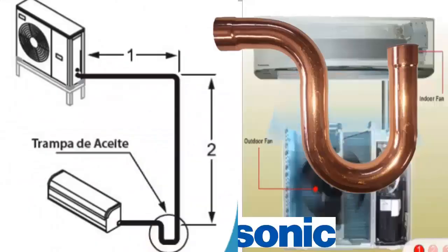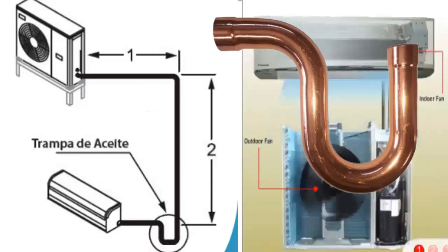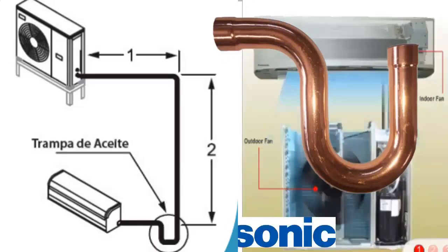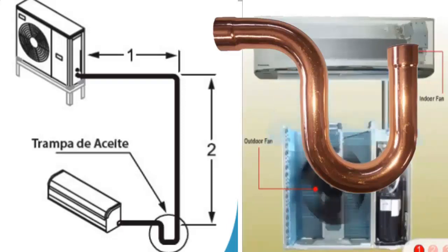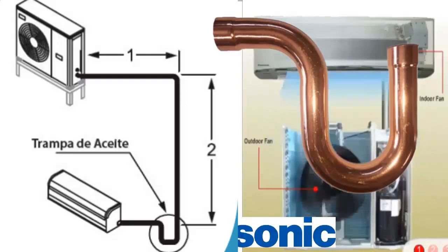Error 8. Forgetting the oil traps. Solution. Install oil traps when the vertical distance between units exceeds the recommended. Check the equipment installation manual.